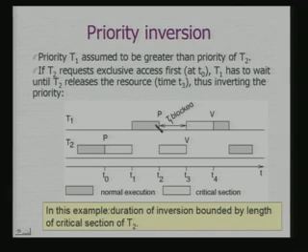So, when this task T1 asks for the resource, it gets blocked and it waits, so it sleeps. And while it is sleeping, the T2 becomes able to be executed. So, T2 gets scheduled and it is now being executed. In this case effectively, although the T1's job is not yet complete, the T2 gets scheduled even though it has got a lower priority.